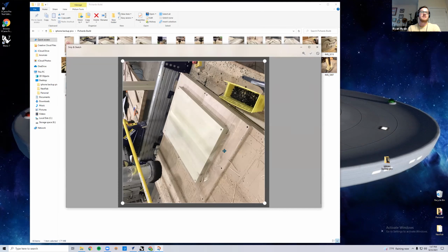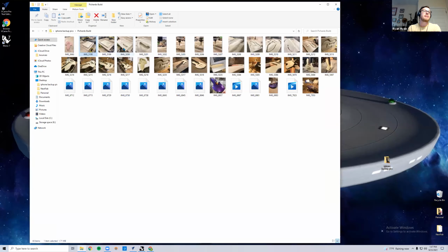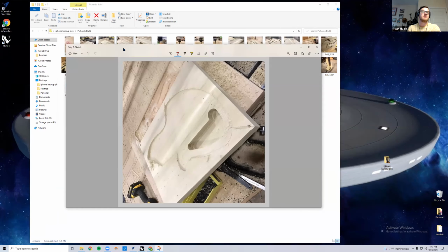So it's like sideways, but this is just the block of wood that I'm going to pop on there. And then this is two-sided machining. So this is after I'm done the back half of the operation, and it looks like the bit dragged on the way in there a little bit or on the way out. So those are some of the things you got to watch out for.